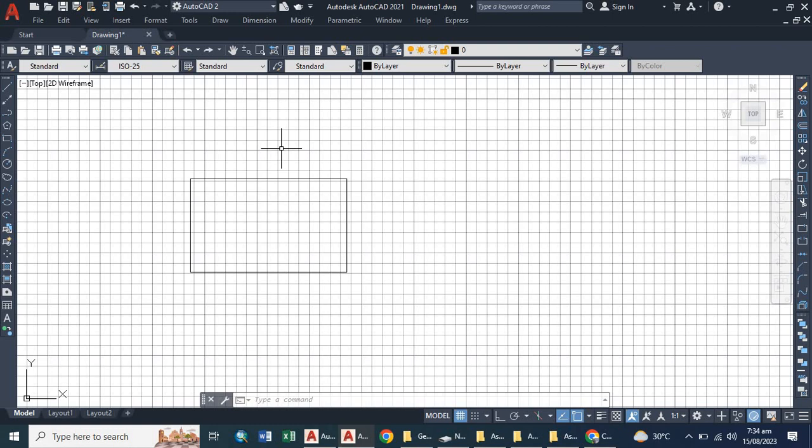For example, whenever we use a solid wall in a 2D drawing, we show it with a symbol like lines. If you want to show some greenery, you can show this with green dots. And if you want to show a solid object, you can also use the gradient command and solid coloring. So these commands are used for that purpose.